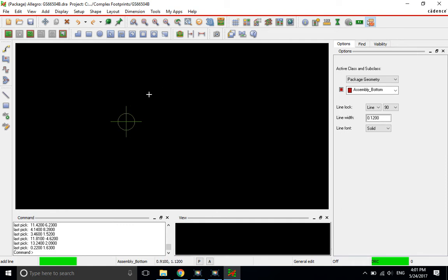I like to just type in the coordinates for when I'm selecting where to place the lines. So if you look in the command window here, whatever you type will show up. I'm going to type in X coordinate space Y coordinate space, and then 0 space 0. What that means is the first 0 is for the X coordinate and the second 0 is for the Y coordinate. And once I hit enter, it gets selected. Notice how it clicks and chose exactly on the 0, 0. This is very useful when you want to make extremely precise selections.